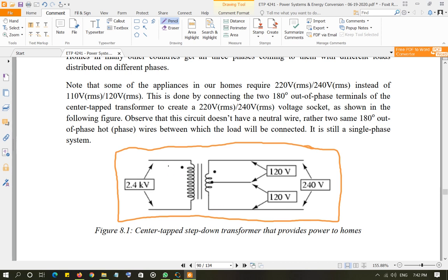You send an electrical AC voltage and AC current in the primary side, and this creates a flux, which is sinusoidal, changing with respect to time, and that flux links with the secondary coil, hence inducing a voltage in it, because the flux is changing with respect to time. And once the voltage is induced, of course, once you connect the load, the current will start flowing from that induced voltage, and your load can consume power.